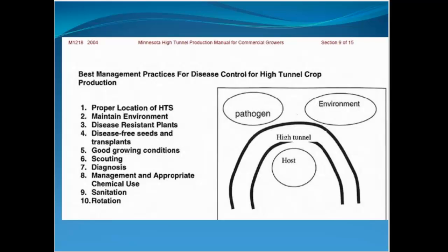Very quickly, that means that if you're south of Champaign in the state of Illinois, you have single bay high tunnels. They're going to be oriented in a north-south direction. As you get into northern Illinois, you'll actually orient your high tunnels to face in an east-west direction. The reason for that is so that we accomplish the most warming early in the spring when the crop is growing.